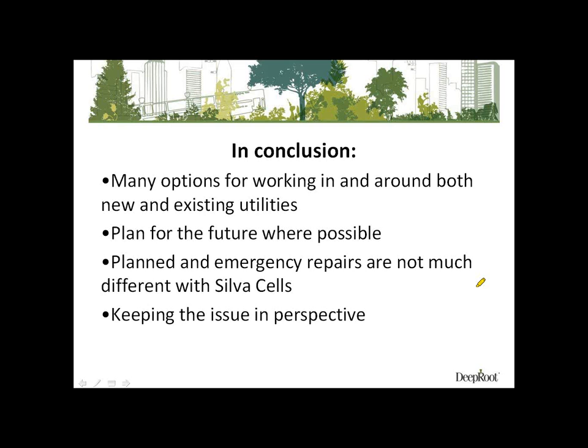One thing I wanted to touch on that the question reminded me of is that I forgot to mention one thing about the Silva Cells. When it comes to doing utility repairs, it's really important to remember that the Silva Cells don't interconnect with each other. Each stack is its own individual stack, so you can go in and remove one Silva Cell, you can remove 2, you can remove 3, but you're not disturbing the integrity of the Silva Cells around you.